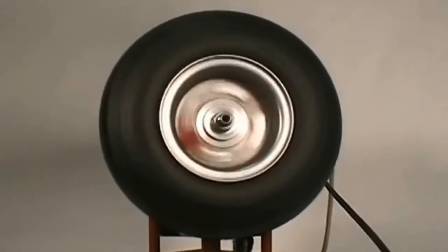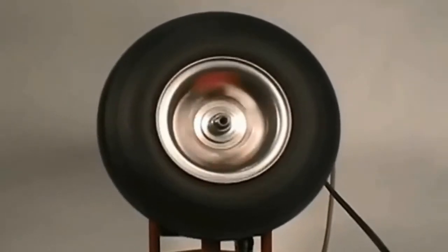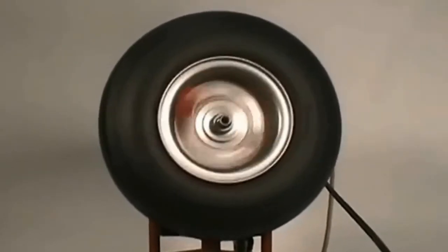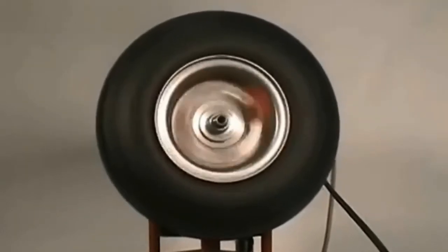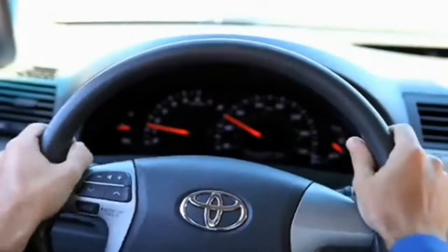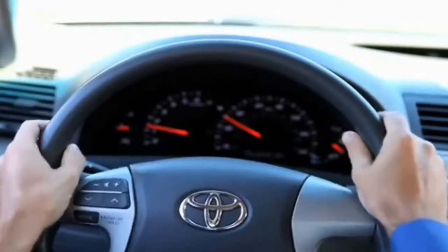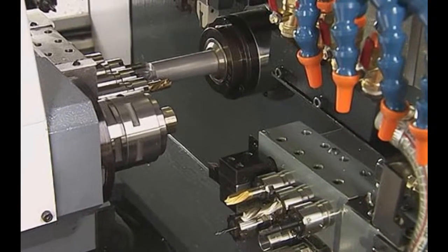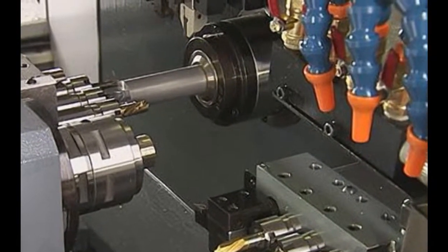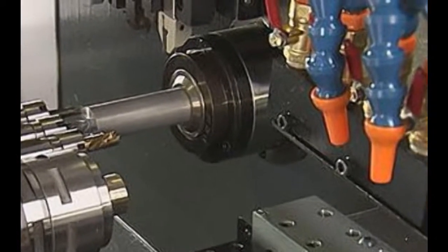Before we look at the bar straightness in detail, realize it acts just like an out-of-balance tire on your car. At some point, the out-of-balance frequency matches the natural frequency of the car and they become additive. When this happens, you get the telltale steering wheel shimmy. Let's look at two examples of how straightness impacts a Swiss machine.